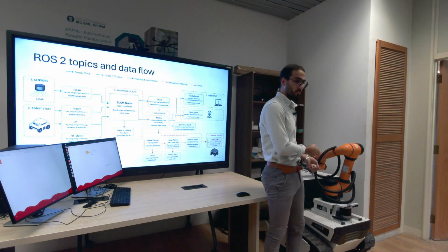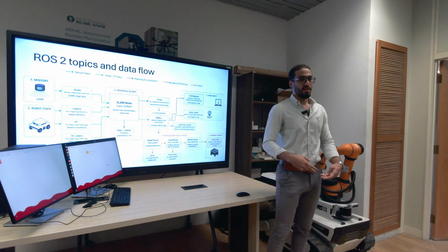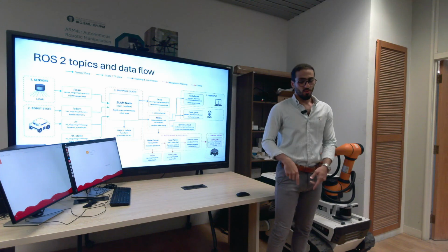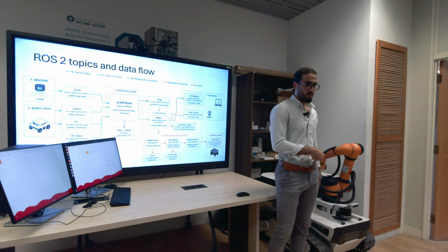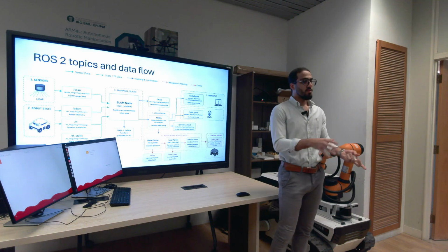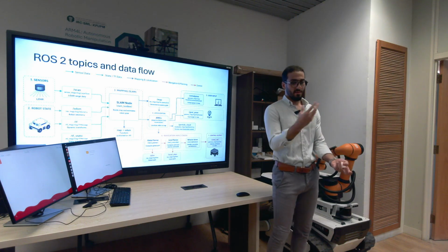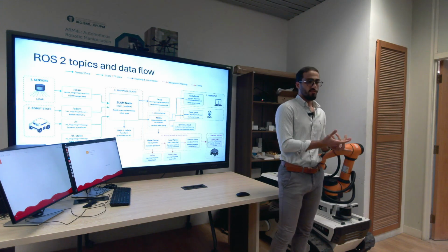But in the case of the robot, it already has the information of the number of steps from the odom because we have the reading of the encoder. So it stores the data coming from the encoder, and it can estimate the diameter of this circle. So now we can integrate building a map while localizing the robot itself, while knowing the location of the robot.